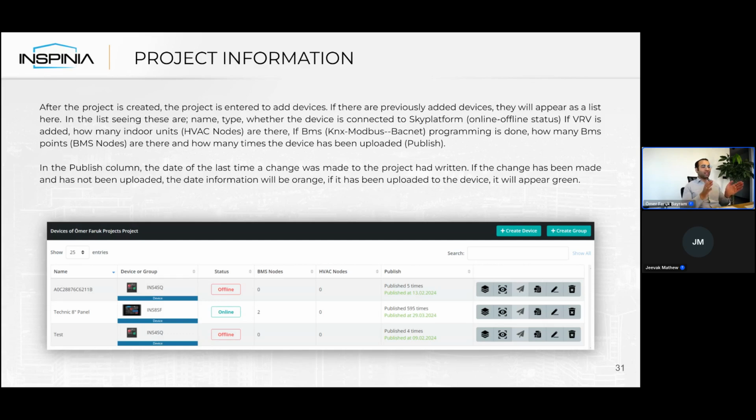For example, you have 10 indoor units controlling over one outdoor unit. We will control outdoor unit, but the critical point for us for license, HVAC license, is indoor unit numbers. We are controlling outdoor unit, but the outdoor unit has 10 indoor units, or there might be 2 outdoor units. It doesn't matter. Some protocol support more than 1 outdoor unit. It doesn't matter. The matter is how many indoor units are there.